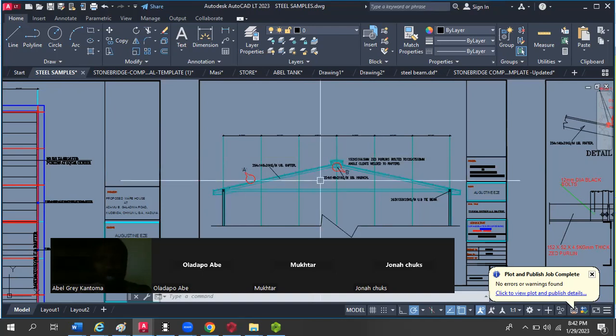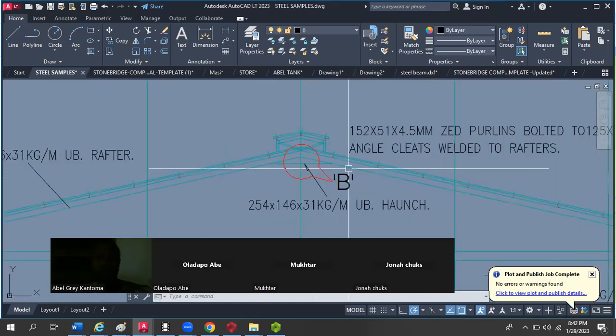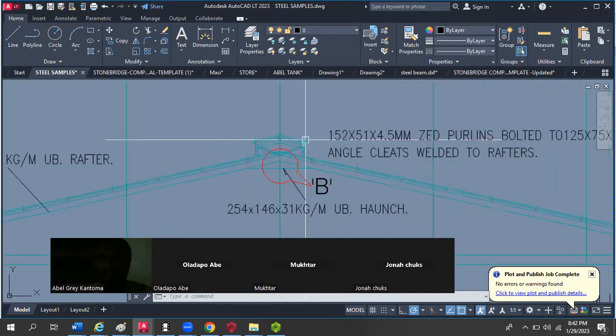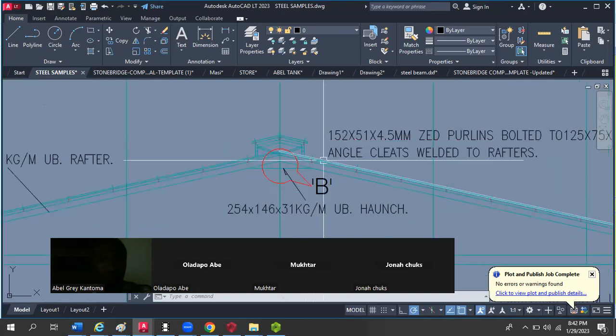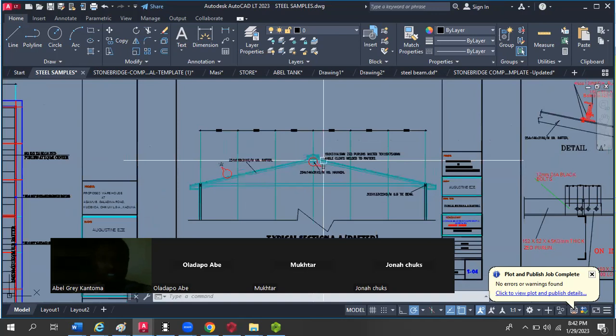So in whatever shape that cross-section is coming, for example, if it's coming in this shape, you have to maintain that particular shape. So your responsibility is to make that particular steel stand, except in a case where you have done everything possible that has to do with the design and it's not working, then you have to call the attention of the architect. Both of you agree with each other. You tell him the reason why there is need for you to change probably the cross-section of that steel and all of that. There are cases like that too.